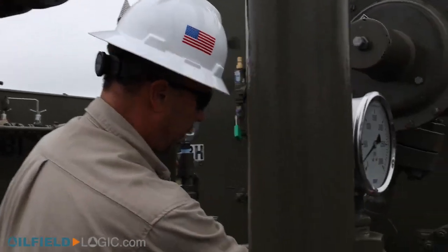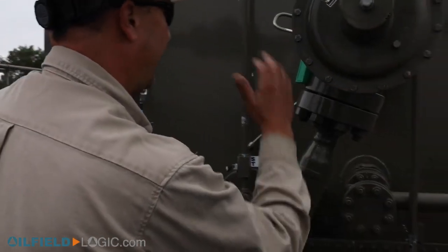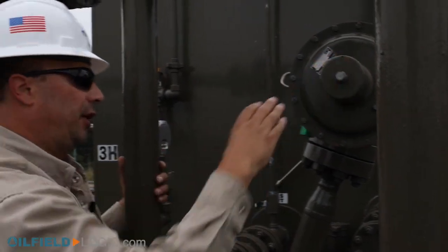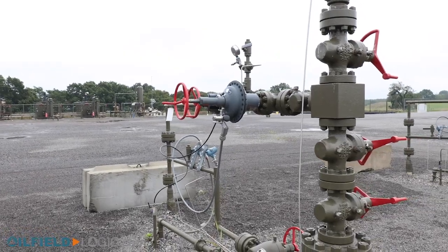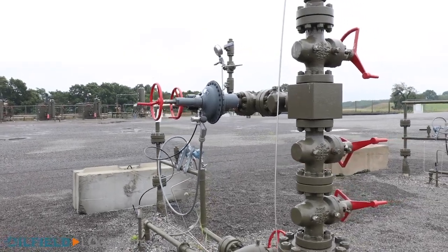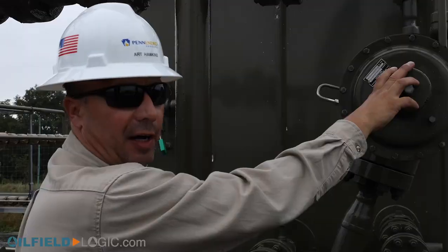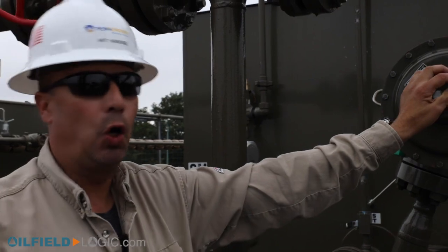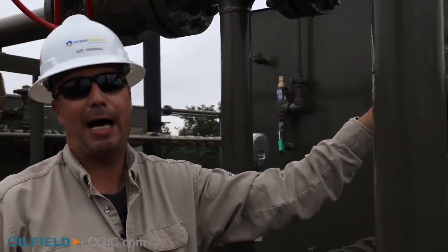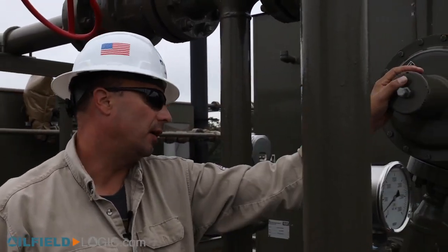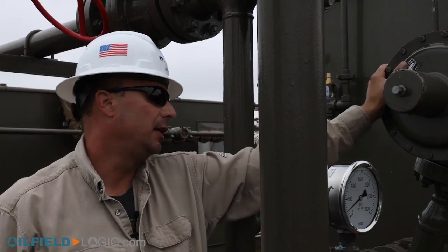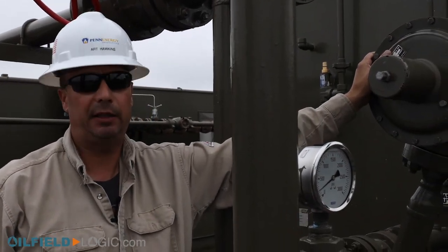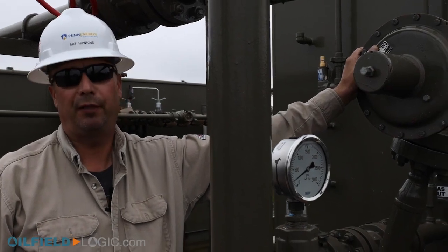Part of after going through the coils and the water bath, we have a second inlet valve here that will shut in relation to the ESD over at the well. This is a second barrier. In case there's valves leaking by over at the wellhead, this will help eliminate any flow that we need to have stopped. So part of our maintenance program, the guys check, make sure there's no leak by checking our safety shutdowns periodically, for sure at least once a month, if not more often.